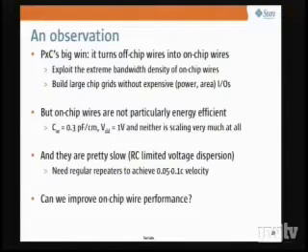That's good because the bandwidth density of on-chip wires is quite nice, but on-chip wires aren't terribly energy efficient themselves. The energy for an on-chip wire to swing is CV squared. Well, C is not going anywhere, about 0.3 picofarads per centimeter, and it's not scaling because it depends on the ratio of dimensions. And V is not really scaling much anymore because VT isn't scaling.